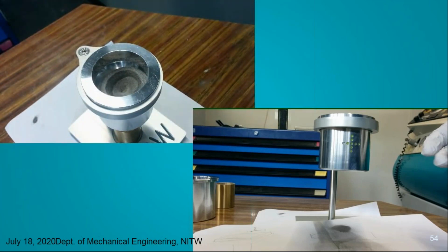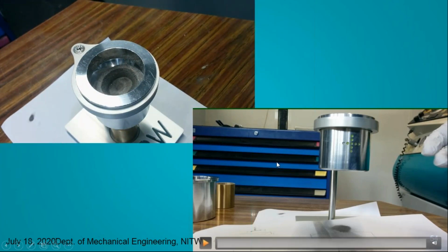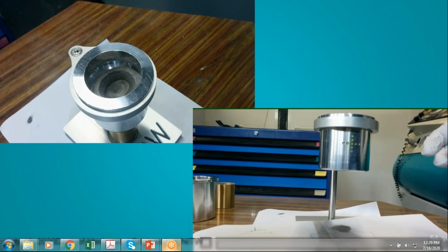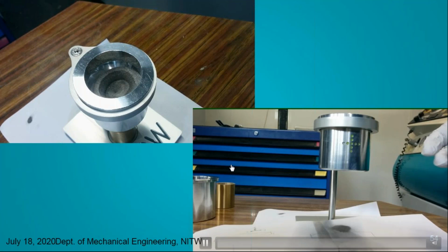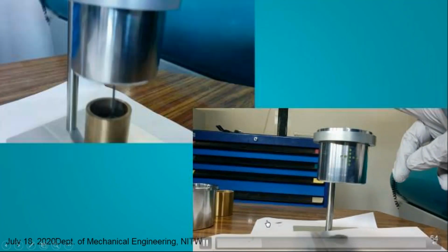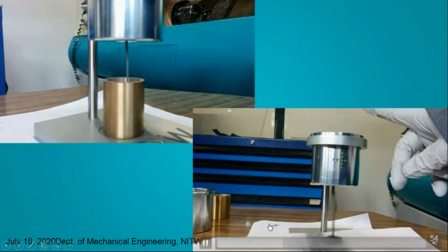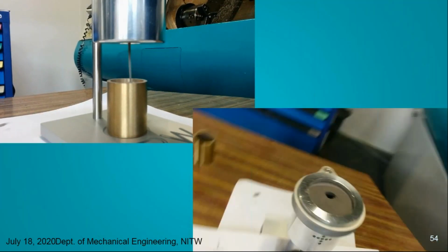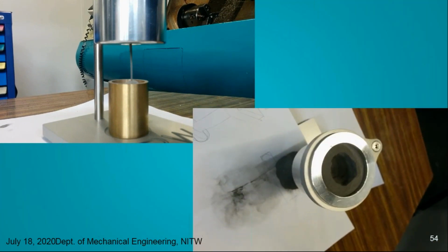And if the powder has cohesive strength, what will happen? You can see in the other video that if it has cohesive strength, the powder is not flowing properly. We have to tap or shake the hopper. When tapping three or four times, it forms a radial formation in the powder flow. You can see I am tapping twice. The powder is not flowing uniformly, and it creates a radial formation in the powder particles. This means the cohesive strength is higher in these powder particles.